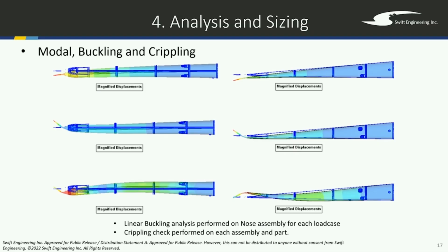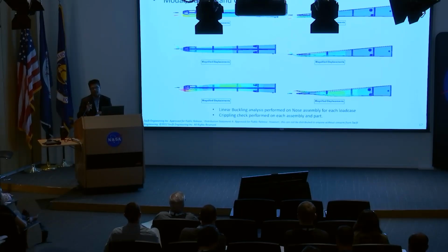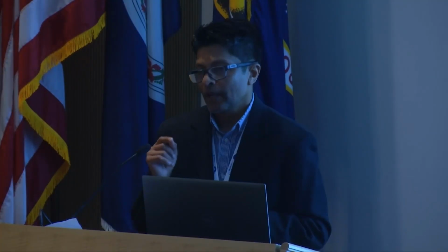These are just some mode shapes, exaggerated, just to give a flavor for what the mode shapes are going to be like. At the very right-hand side of this nose cone, that attaches to a metallic bulkhead, which is part of the main fuse. And we're only allowed to have one row of fasteners. So that was the thing that kept us awake. It was like, why can't we have 2 rows of fasteners? And they didn't want 2 rows of fasteners. That was just one row.